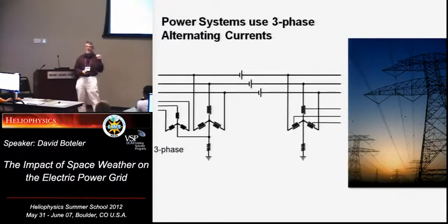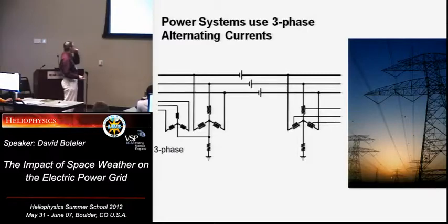Just by knowing about this, you can get a lot of insights, because sometimes in your street, if there's problems, there might be a blackout or something, you can have every third house out. And you wonder, well, why am I out, but my neighbor's got power? Well, every third house is on one phase, and that's what's had a problem, and the other houses are on the other two phases.